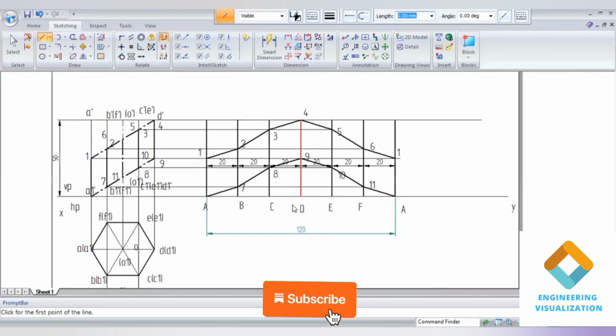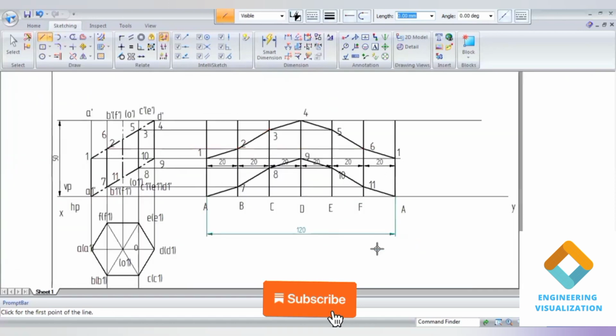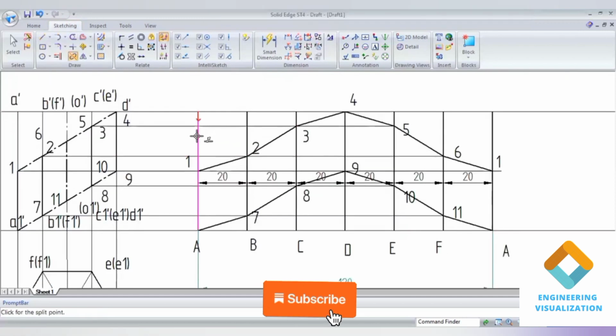You can see that. Now only the cut part we have to make dark, and the other part we have to make thin. For that we will be using the split command. By selecting it we are going to make those lines thin lines here. Using the split command we can show the remaining part in thin lines.